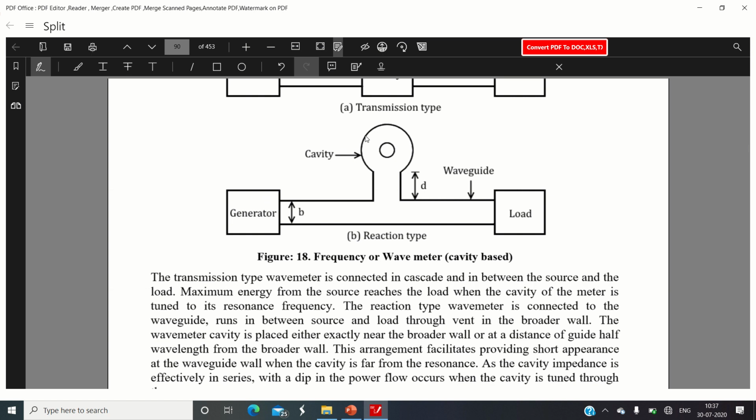So we have a rotary arrangement over there. Now, if possible, when we start with our practical session using the test bench of microwave in our laboratory, then we will actually perform this particular experiment. But for the time being, let me tell you how this operates. If we want to measure the frequency generated by this particular generator, what we need to do is simply rotate this meter either in a clockwise direction or in an anti-clockwise direction.